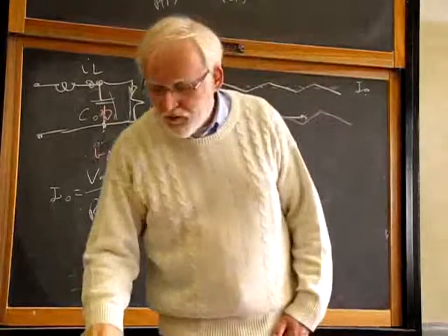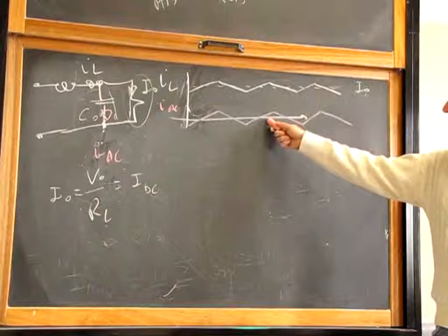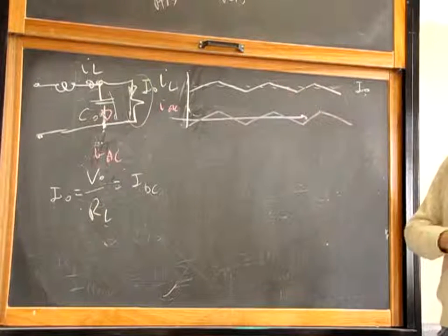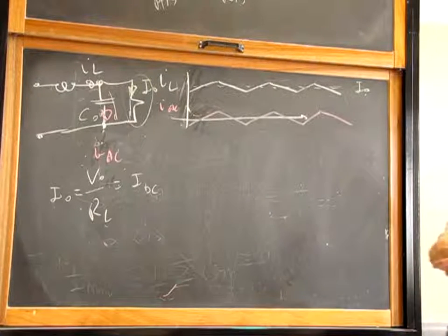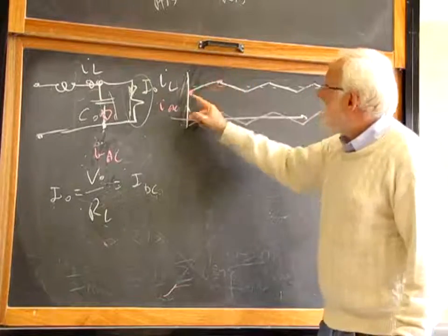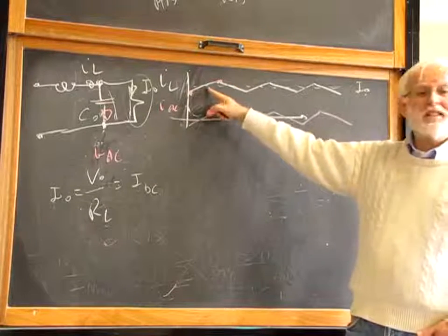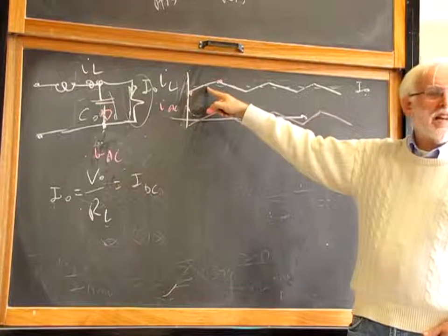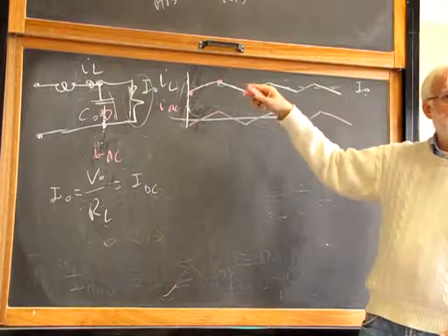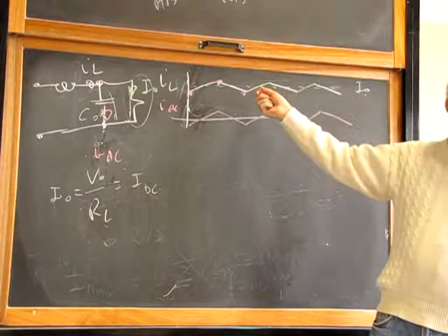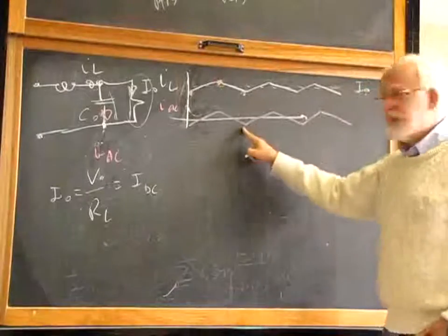Which RMS value is easier to evaluate? This red or the white one? White. White means that we have to take this segment, write down the equation for this segment, and square it. And this segment has an equation that is something like Ax plus B. And then we have to write down a different segment. Okay, see you tomorrow when you get to this result. It's far easier to find, in this case, the RMS value for the red waveform.